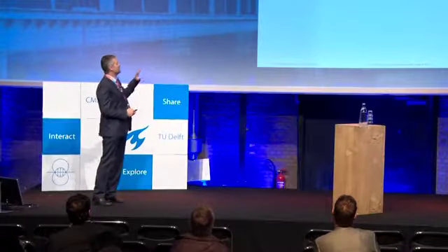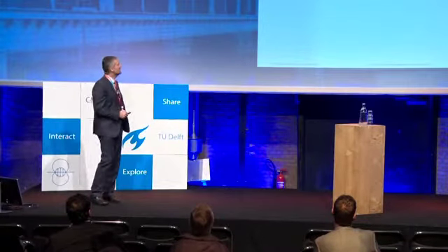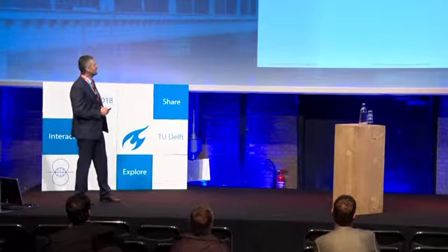One slide about the state of the art when we talk about assessment of running gears with respect to wheel and rail wear and RCF. Many researchers use quite simple D-gamma-based approaches, where they have a certain vehicle, one combination of wheel-rail profiles, one speed, certain adhesion conditions, and then they calculate the D-gamma values, and based on those values, they assess whether the running gear is good or bad with respect to these topics.